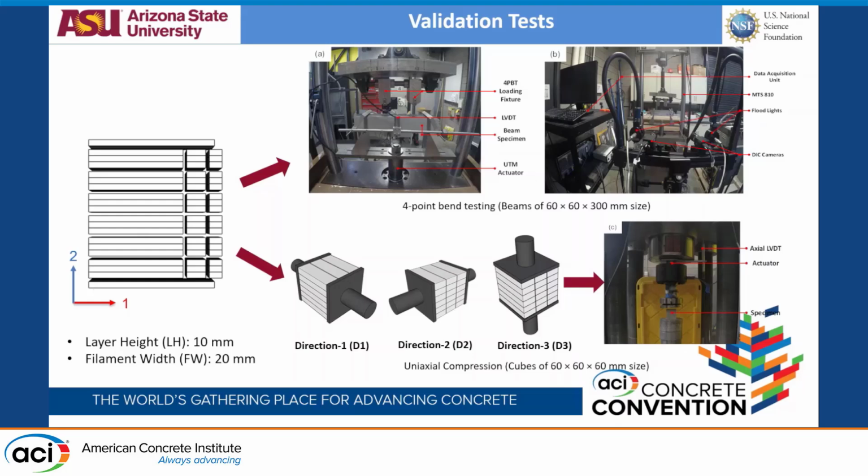Do we assume a certain kind of strength for the filaments? The crack does not technically go through the interfilaments always, resulting in a more heterogeneous kind of strength result that is neither of the interfilament nor of the bulk filament. So I'm staying away from D2 and D3 for the beam test.